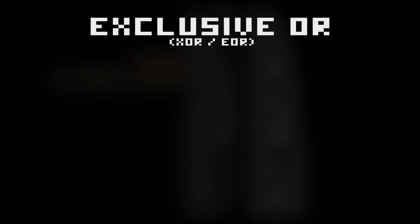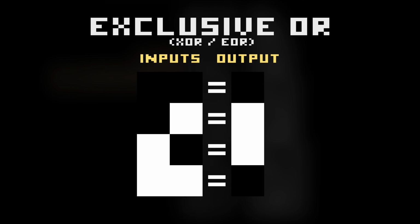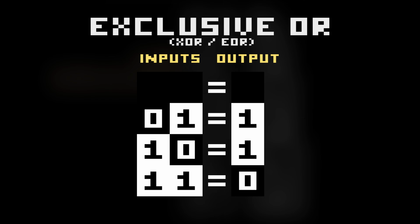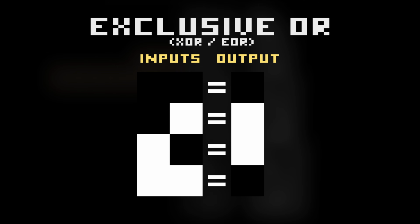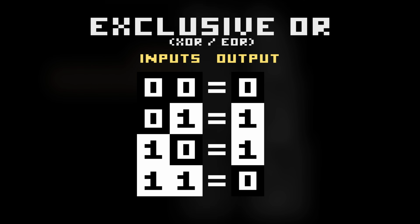Well, when it comes to flipping bits, we should look towards the exclusive OR operation. This is a binary operator that takes in 2 bits as inputs and outputs a single bit as a result. The definition is often stated as something like, the output is 1 if either one input or the other is 1, but not both, hence exclusive OR. However, sometimes a better way of thinking about it is that one input is the base and the second input is the mask. If the mask is 0, the output is just the base input. If the mask is 1, the output is the opposite of the base input.